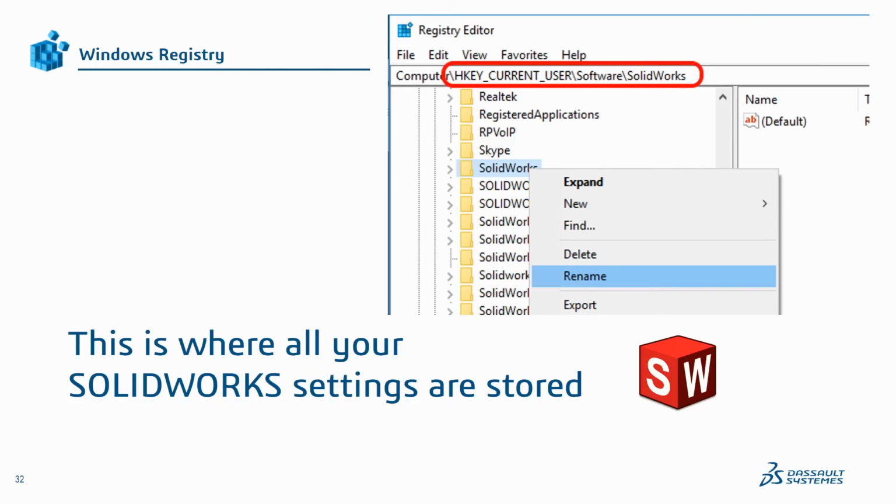So it's a tips and tricks. It could go either way, but it's a really good thing to know how to do and something that I do pretty regularly, especially when I start running into abnormalities in the software. If I'm working with sheet metal and I go file, make drawing from part, and SolidWorks crashes, and I do it again and SolidWorks crashes, it's almost certainly registry. I go in, rename the registry, bring it up again, the same part file, make drawing from part, it works fine. Right? I corrupted something in the registry that function is making a call for.